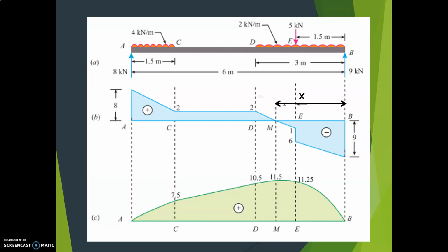Now what you have to calculate is where the maximum bending moment lies. Maximum bending moment always occurs where the shear force changes its sign.